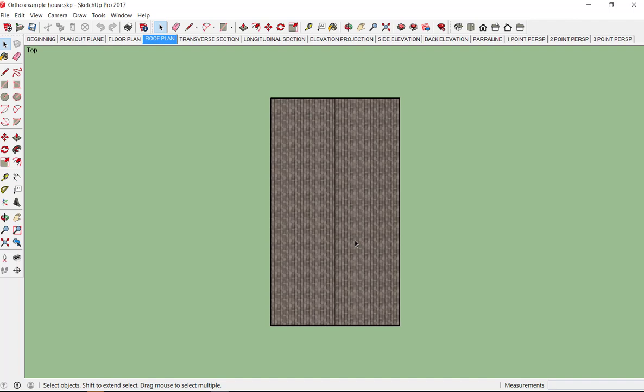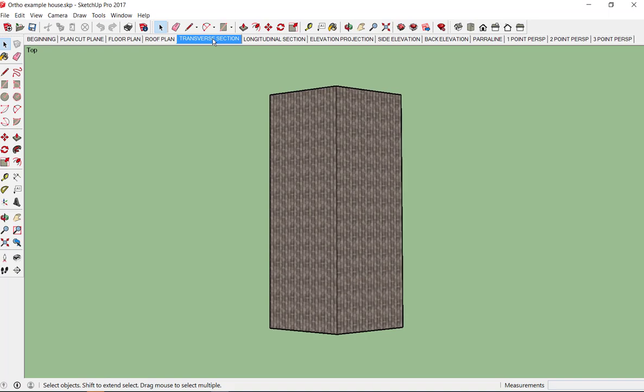And then a version of that is a reflected ceiling plan, which is if you cut the floor plan and you put a mirror on the floor and you look down on it, you would see what the ceiling was reflected in it. So that's how you draw what the ceiling is on a floor plan. And the other kind of section would be the section that you cut through the building either to show the spaces or to show how the building's constructed. So let's show you an example of that.